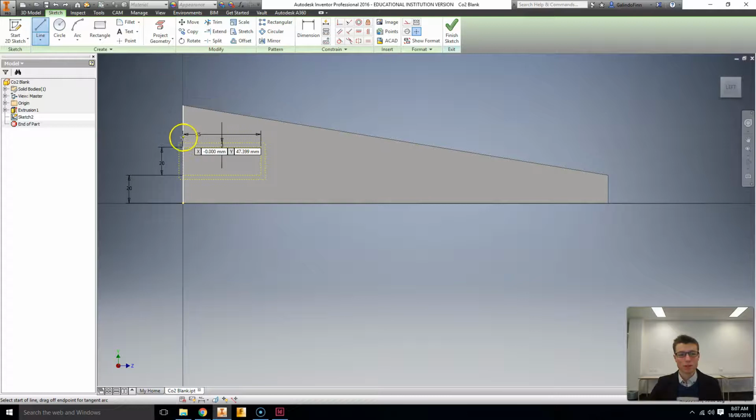Okay, starting from the back edge here, like normal, I'm going to go from about here, and I'm going to select about just in line with the edge of my white dots here, and it actually locks on, as you can see, with the black line now. Clicking and holding, I'm going to pull down a rough point to about the mid area, and then hold and pull down again and change that so it's kind of about this orientation here.